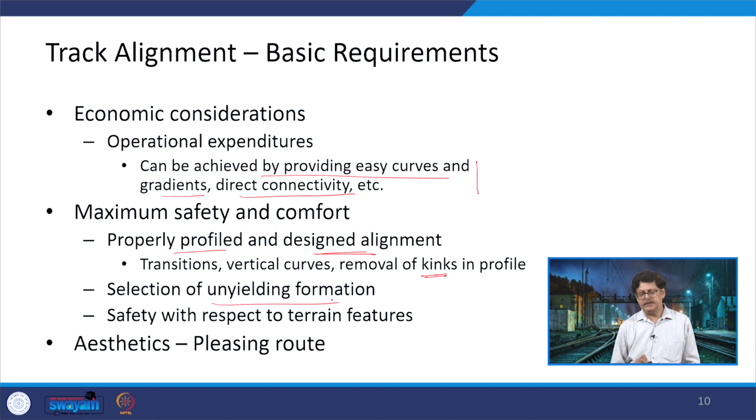Selection of unyielding formations, because yielding formations will keep creating problems in terms of maintenance requirements. Safety with respect to the terrain features: if you are in a hilly terrain, what are the safety measures which need to be taken care of? That also becomes an additional feature there. And finally, aesthetics is one important thing. Whatever the route is, it should be aesthetically pleasant.